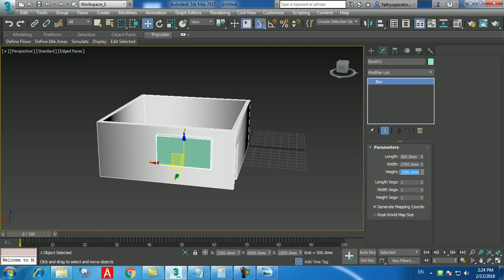How do I modify the window? It's not a pairing. There's only the Boolean layer. So first you have to select the wall, then it will come. No, I just want to look at Boolean. You want to fix the line, the height of the window, downward line. It's already made Boolean. Look. Once you make a Boolean, the window will become Pro Boolean. Okay. Control Z again.